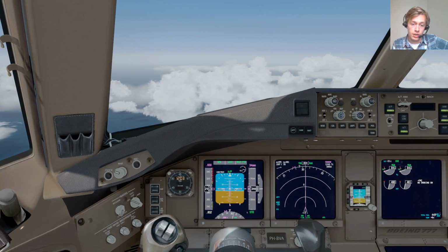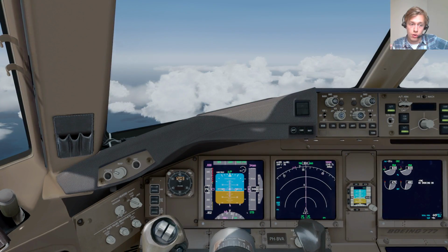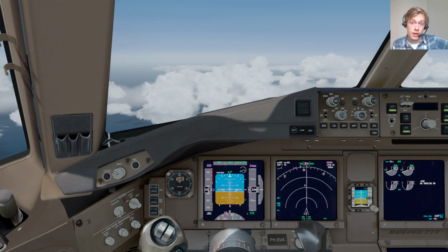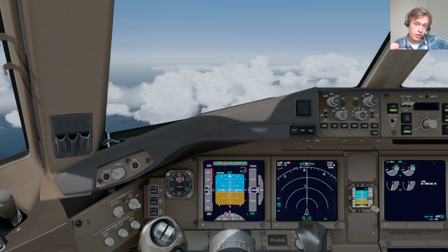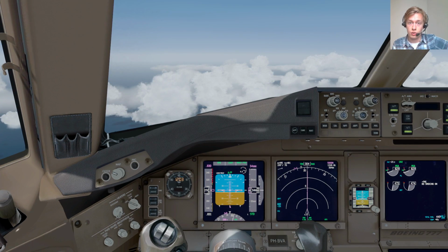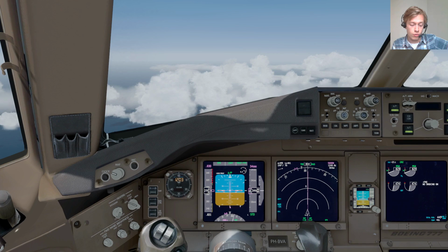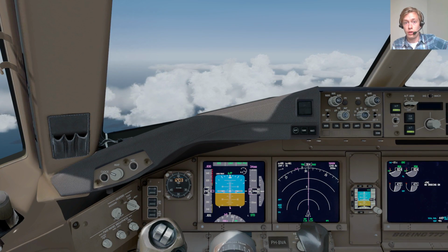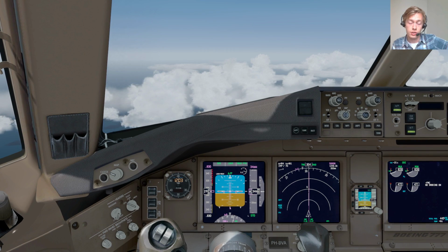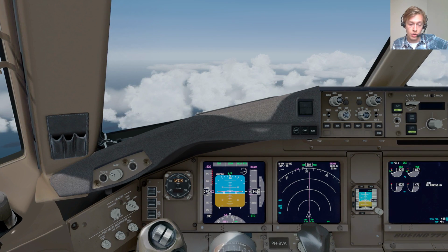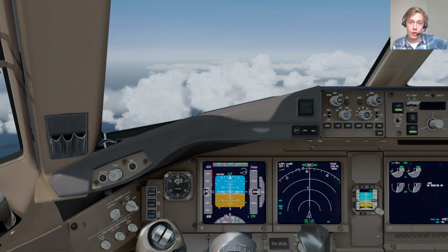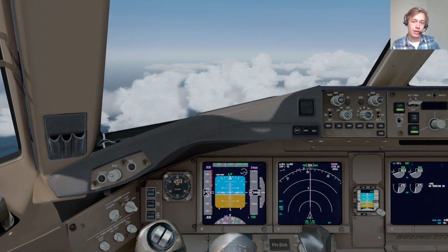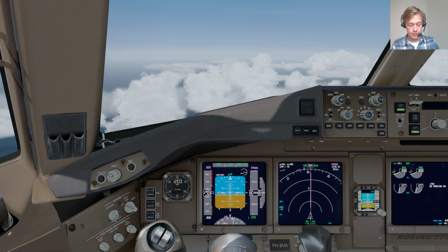Another thing to mention is when your destination is quite close to the coast and quite close to the NAT track, you're not actually allowed to start your descent in the NAT track, or in the oceanic airspace. Descents in this airspace are for emergencies only, okay, so do not say something like a KLM 641 requesting descent while you're still flying on the NAT track. That's not the way it goes. So you have to be in domestic airspace before you do that.